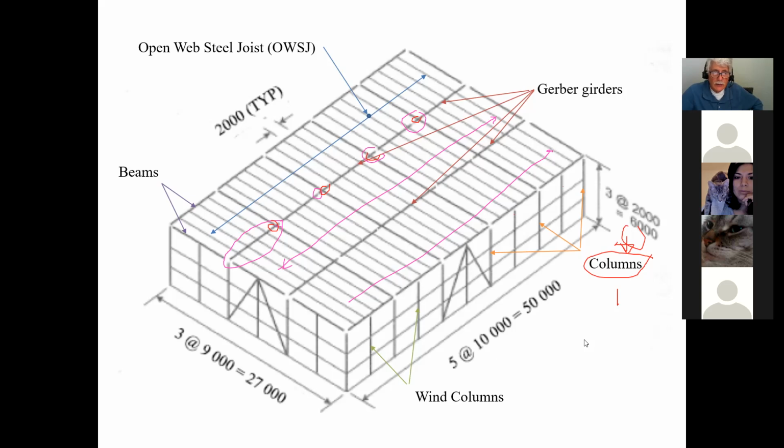And then after that, we're going to be designing these braces. Okay, what do the braces do? Well, all the lateral loads that are imposed on our structure because of wind or earthquake get transferred to these things, and these things transfer the loads down to the foundation, and hopefully everything's going to be stable and won't collapse on you.